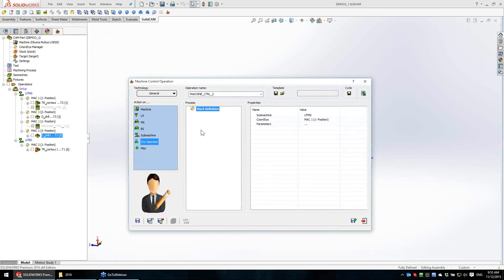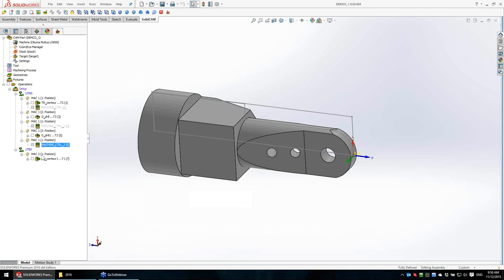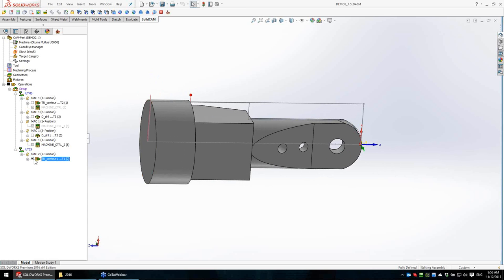CNC operator for now. In the previous webinar, you already saw how to transfer a part from one spindle to another with the whole process: moving the back spindle, unclamp, clamp the part, release from the main spindle, retract, and all the cycle. Now I will use CNC operator, manual stock transfer, to the back spindle. Save and calculate. Now the operation doesn't have a red dot. The operation is correct. I have a stock on the back spindle, and I can work. You can see the toolpath.